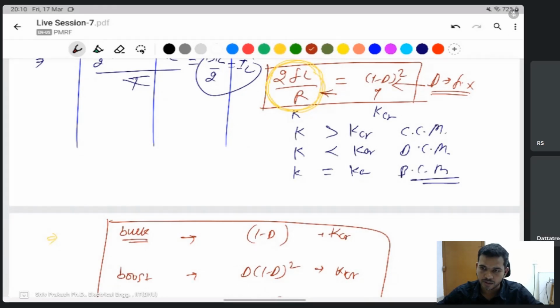It is load dependent. If a light load is given, the whole converter goes into discontinuous conduction. Otherwise it is continuous conduction mode. Then everything depends on R. If you are less than, that means this one is greater. Less than means load is more, current is more.